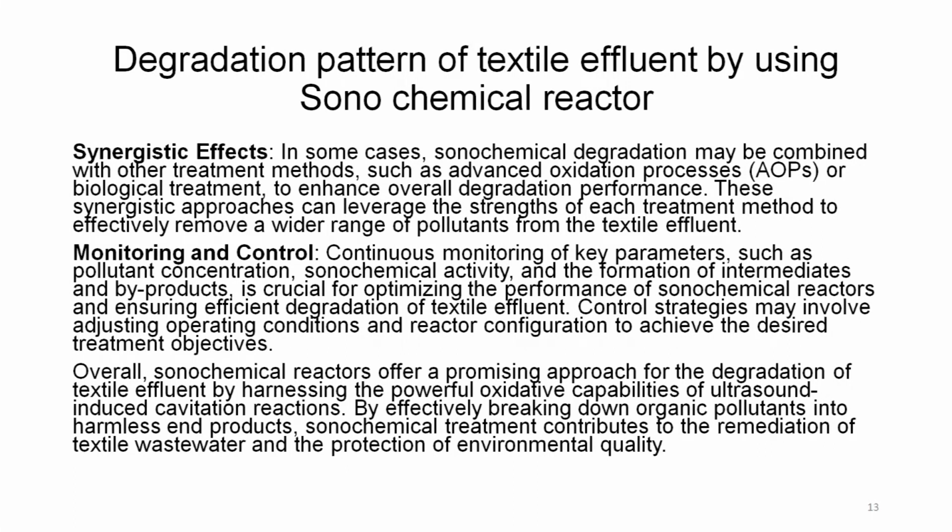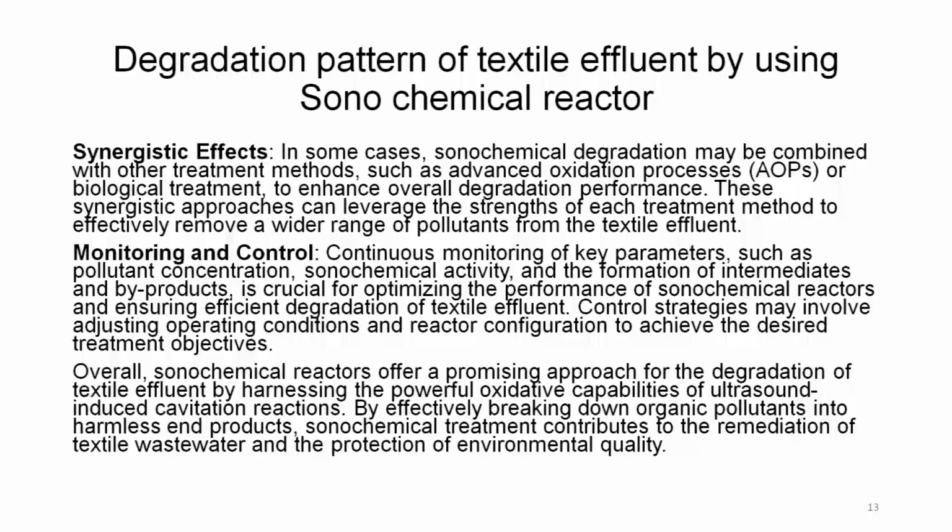So, what happens is that if sonochemical reaction is combined with either a biological system or any of the advanced oxidation systems like Fenton reaction or hydrogen peroxide UV and those kinds of reactions with ozone, then it can further enhance the degradation of the organic pollutants.